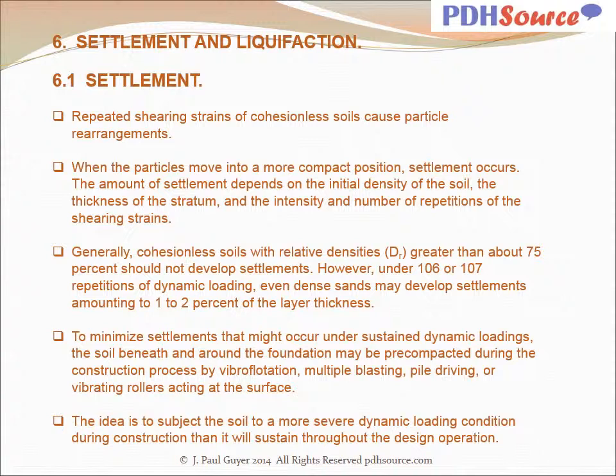of the layer thickness. To minimize settlements that might occur under sustained dynamic loadings, the soil beneath and around the foundation may be pre-compacted during the construction process by vibroflotation, multiple blasting, pile driving, or vibrating rollers acting at the surface. The idea is to subject the soil to a more severe dynamic loading condition during construction than it will sustain throughout the design operation.